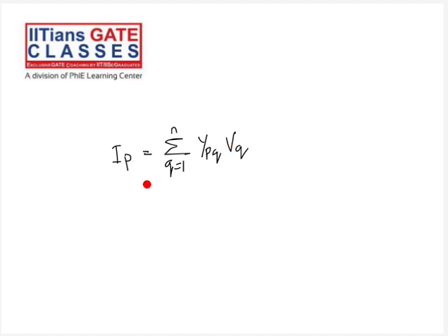Let's summarize what we looked at in the Y bus earlier, right? As the number of buses increases, a lot of the interconnectivity becomes less, and a lot of the off diagonal elements become zero, right? But if you add an inductive element to the system, the Y11 would become bigger, and if you add a shunt element, this Y11 will become smaller. We saw all these things, right?